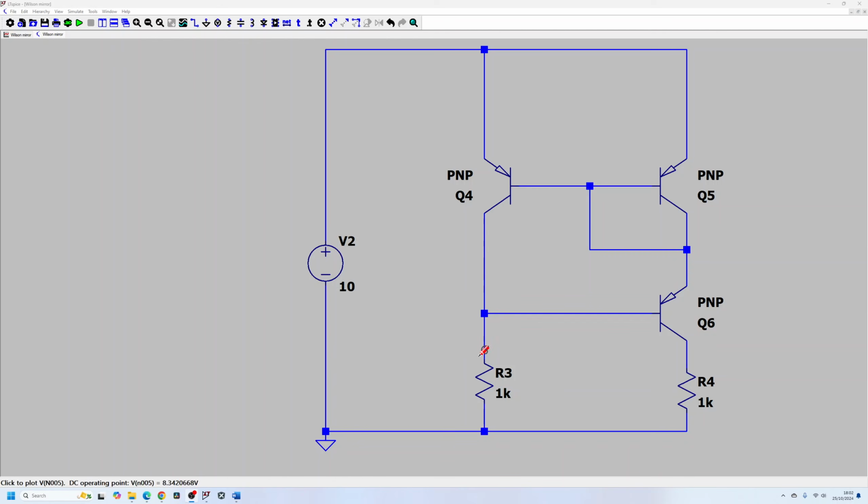And using that knowledge, you can calculate the setting current for this circuit. If you have 8.8 volts over here, then you can basically choose a value for the resistor such that you get the current that you want from this junction over here. Obviously, you're going to have a little bit of current flowing in this direction. Both Q4 and Q5 have fixed emitter and collector voltage drops. And you can think of Q6 down here simply as passing the current through a load that varies, basically.